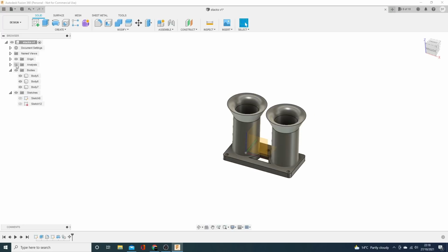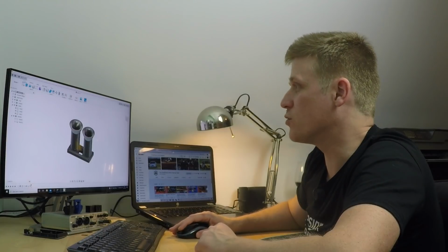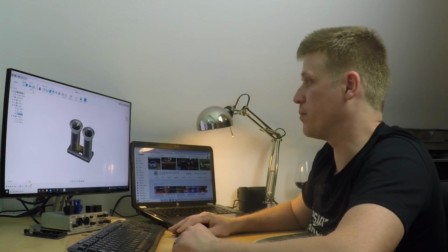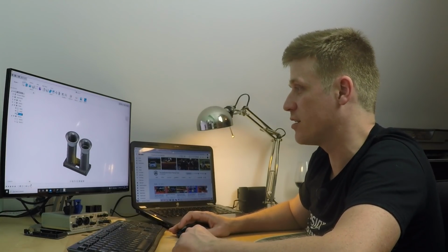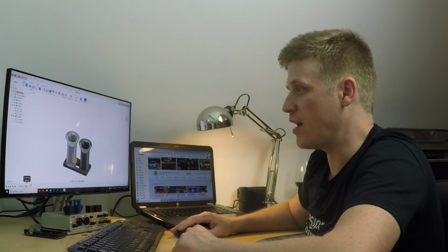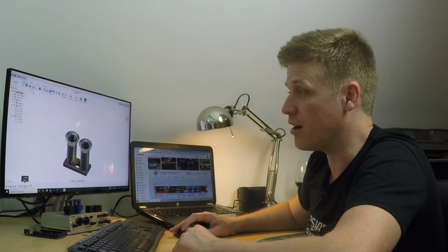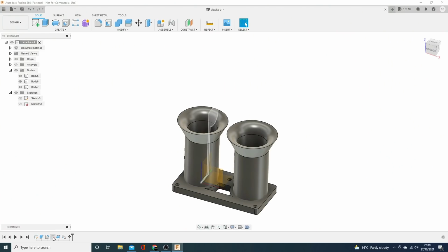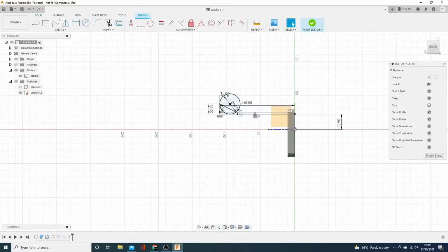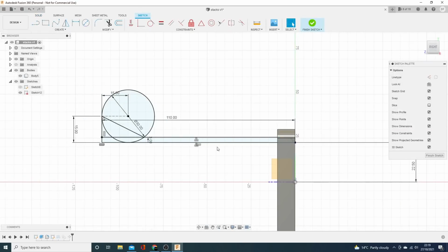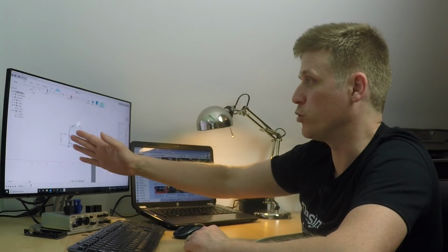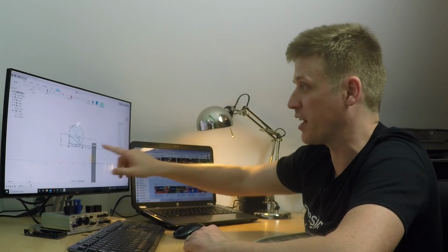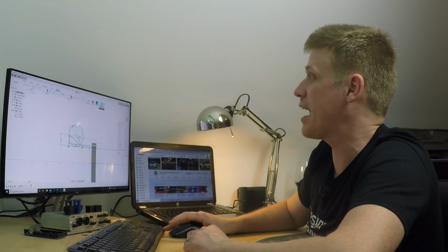You go to the analysis section there. Now the reason why I wanted all of that geometry fully constrained is because if I want to go and change the length, I can. I don't want them 110 mil. I want them a different length. And because everything got constrained coming out on that first length, if I change this, let's say to 60, it all just comes back in because it's all built logically off that first route out.